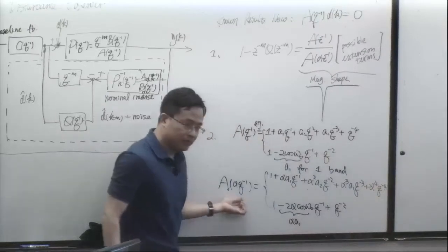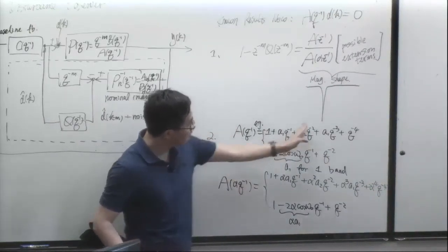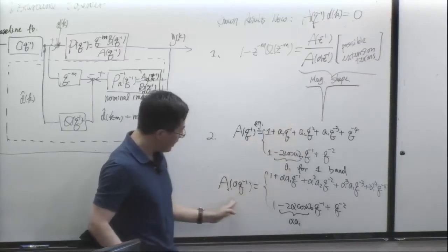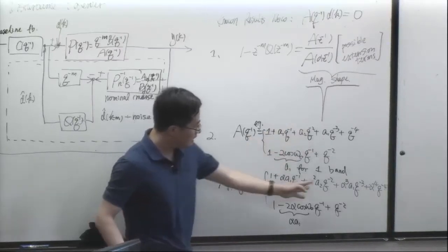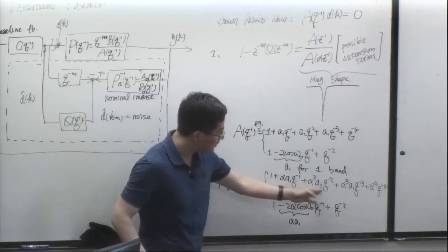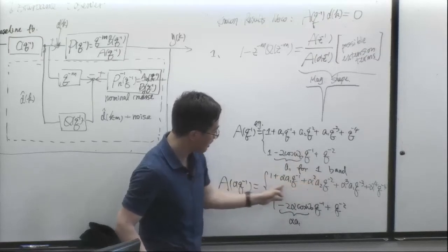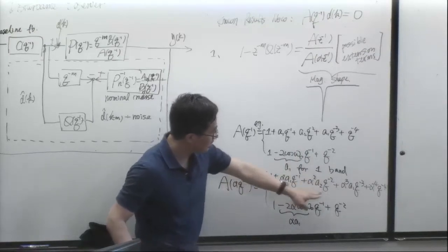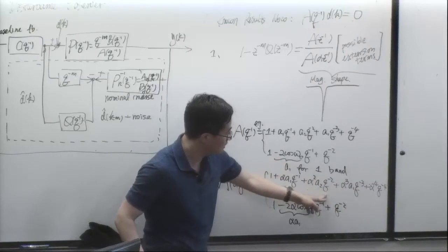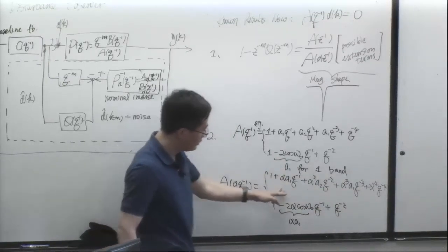Okay, so from here, be a little careful. A has this mirror symmetric structure, but A alpha Q inverse no longer has this mirror symmetric structure if n is larger than 2, if you have 2 or more disturbance frequencies, because alpha is going to be scaled as your order of Q increases. All right, so be careful when you do the programming here.